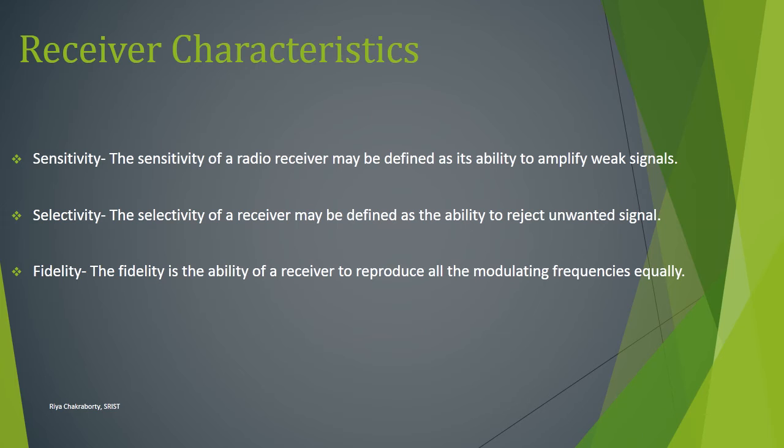Now, fidelity. The fidelity is the ability of a receiver to reproduce all the modulating frequencies equally. The fidelity basically depends on the frequency response of the AF amplifier.